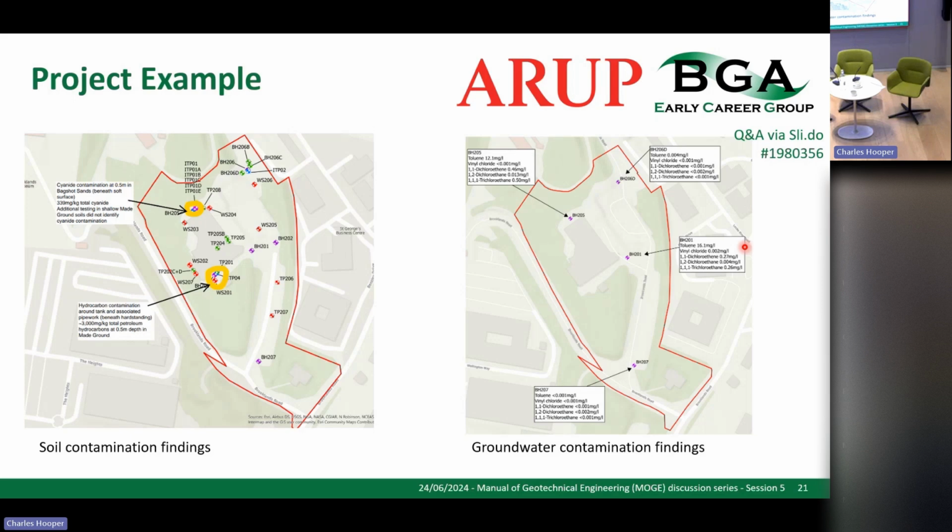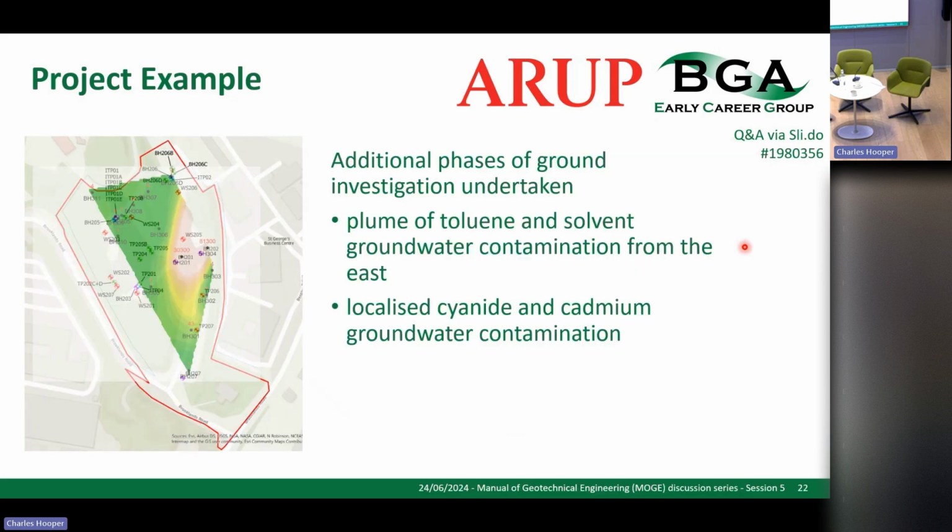And then the big issue for the site was the quite widespread groundwater contamination, toluene, chlorinated solvents, very high concentrations of 12 milligrams per litre, which is substantially above the limits that you're allowed for it. And we had no known source really, so we had to go back. And then we looked again at some of the planning reports available for the adjacent sites and discovered one of them had been a yard that had some remedial works done in the 90s for similar contaminants, as it turned out, and had supposedly been passed. But looking again, we then designed a second phase of investigation.